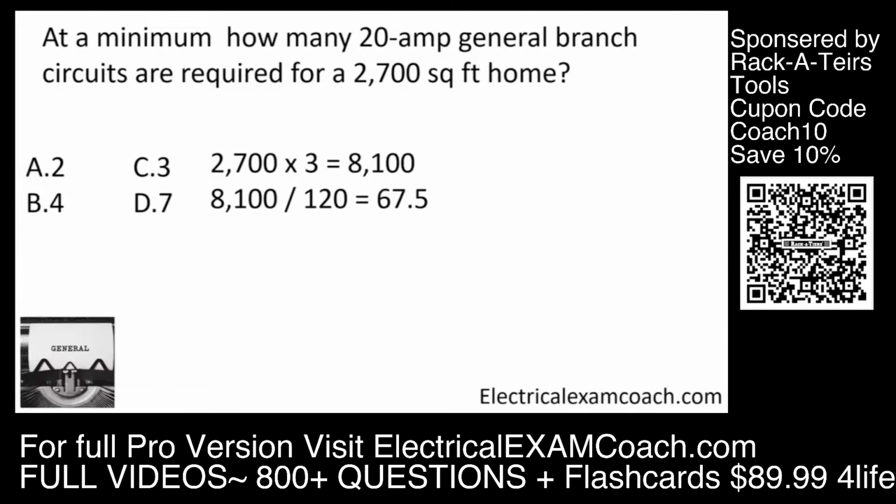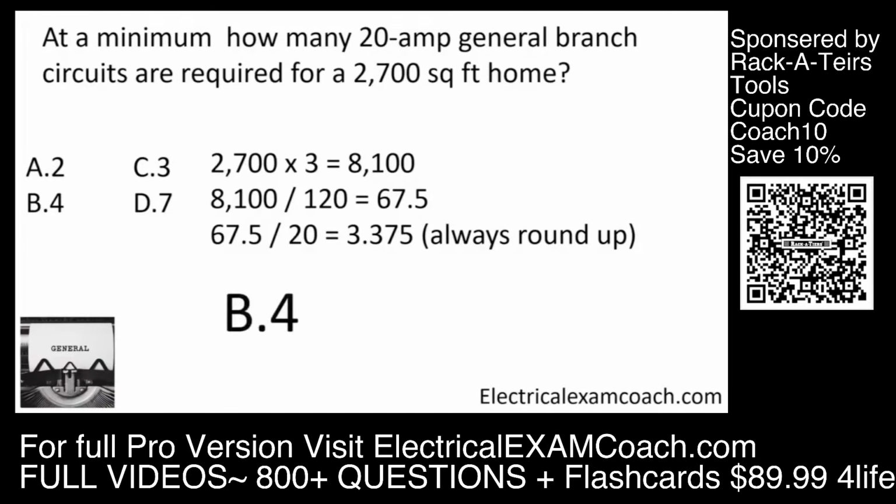Then we're going to take that and divide it by whatever size branch circuit that we are going to be installing. In this case, they want to run 20 amp circuits, and that's okay. Here we go. We take our 67.5 divided by 20. That lets you know at a minimum for this home, you must have 3.375 circuits. And we're always going to round up because you can't have a piece of a circuit. So the correct answer would be 4 for this home.